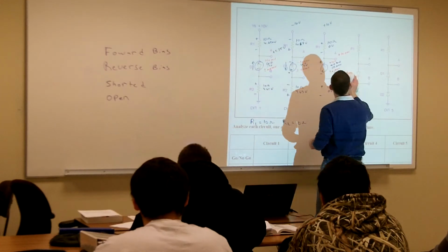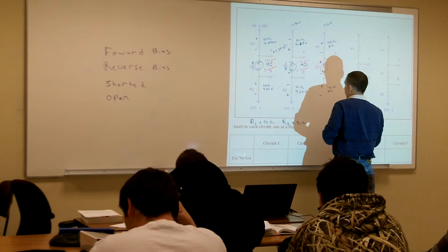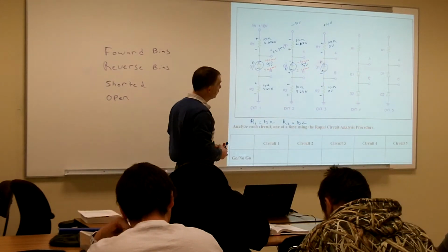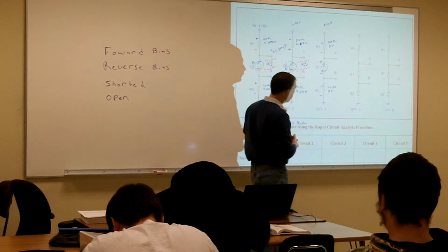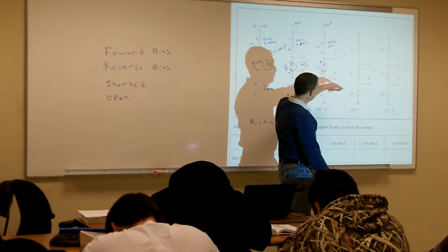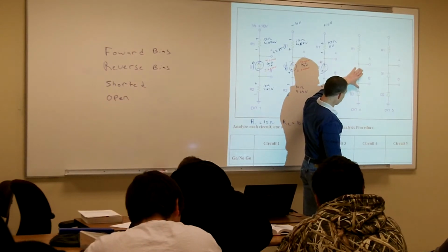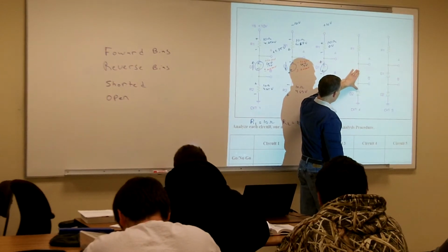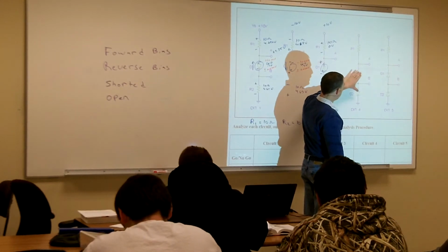All right, and these next two, I'll even give you a little heads up, are a little tricky. And this is where, when we're working with solid-state devices, it's going to be very critical, and I kind of mentioned it in DC a few times. When we're working with solid-state devices, it's very easy to turn on another device by using our voltmeter.